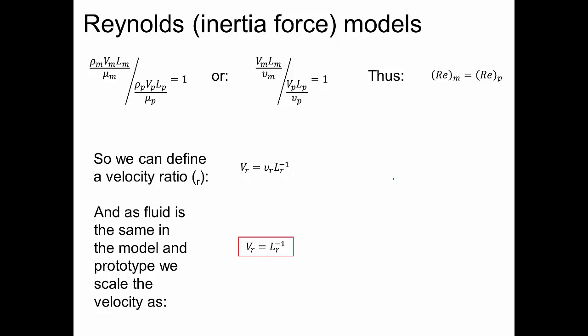Okay, this is my other problem in my line of research. When it comes to flow over the turbine blades, we need to scale using the Reynolds number. So we need the same Reynolds number across the blades in order to get similar flow. So now we've gone from looking at the whole channel to a smaller part. And again, Reynolds scaling is very important when you go into wind tunnels for aircraft, Formula One, any other application really. So here now we've done exactly the same.